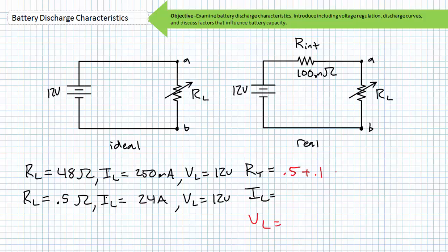Consider a 0.5 ohm electrical load connected to the battery. In this case, the source would see 0.1 plus 0.5, or 0.6 ohms, of total resistance. Accounting for internal resistance made total resistance increase, only this time the 0.1 ohm internal resistance in proportion to the 0.5 ohm load resistor increased at a much greater amount.